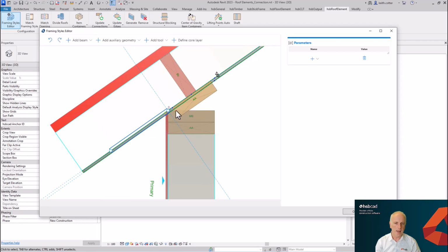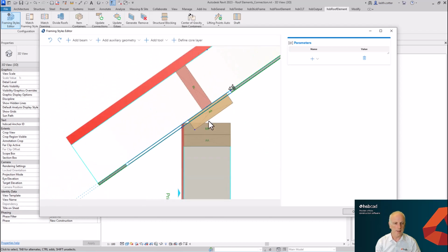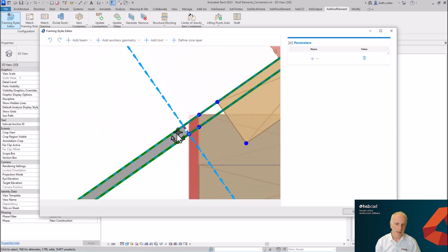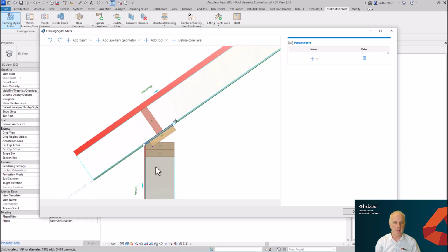particular beam and to this particular sheet, and we're going to say I'm going to add a sheet cut here and anchor it into that, and I'm going to add a sheet cut here and anchor it into this and pick the sheet in question. So important that you anchor it in, and when you've anchored it in you pick the actual sheet to complete the process. So in reality this is now our knee wall connection, all is good.